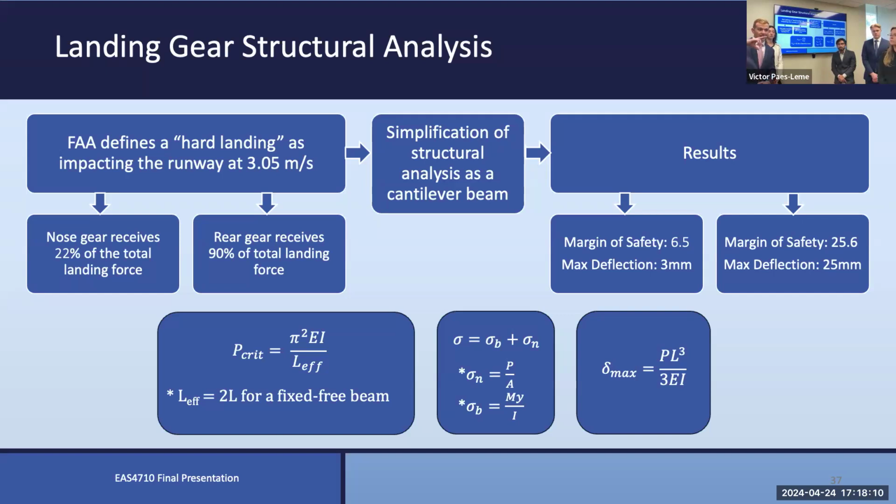So we did approximate it as a 45-degree angle beam, but again, your point still stands. Is it still that equation? I don't think so. Well, you'd have a 45-degree beam and then it's mounted here. So if you just rotate it, it's still a cantilever beam. Do you see what I'm saying? Your boundary condition is here, your beam goes like this, and the force is applied here.